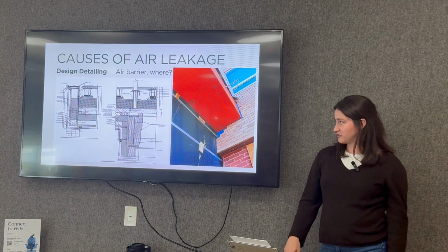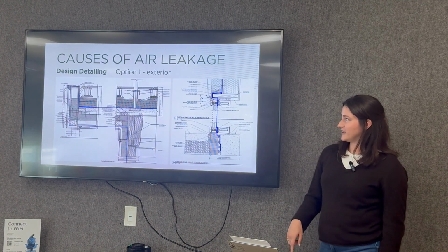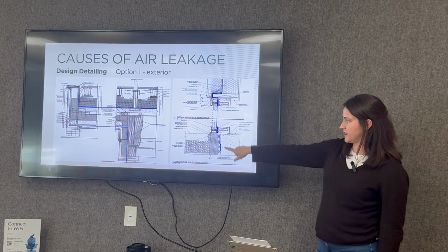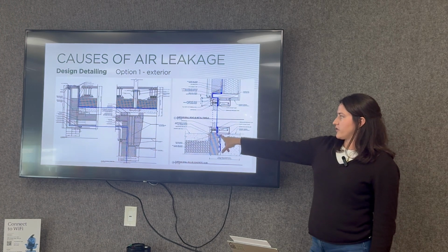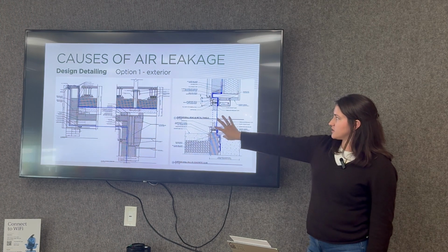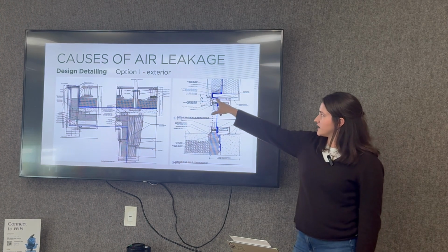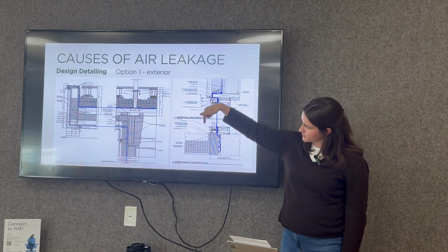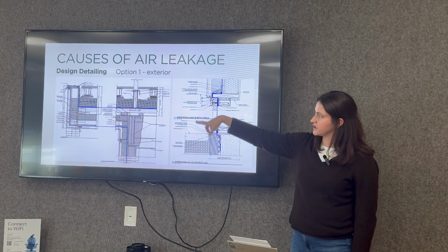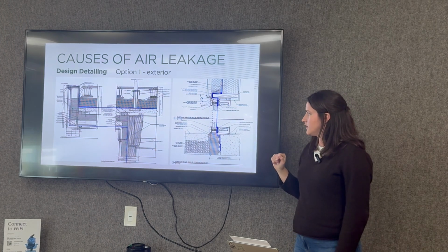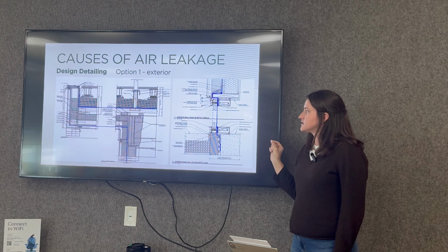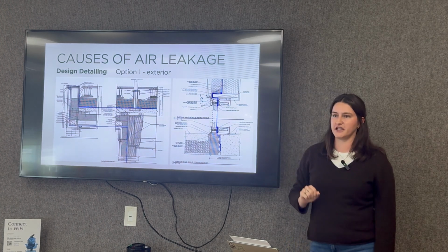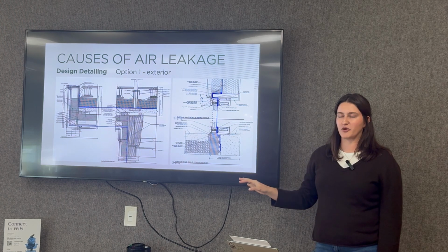Yeah, so that's one option, providing your air barrier fully at the exterior. So you're connected here up with a membrane and then a silicone sheet to the curtain wall, which is your air barrier, and then you connect it with membrane up to the soffit. And then your exterior soffit board is lined with the air barrier, which then connects to the roof vapor barrier. Does anybody see how this in and of itself could be risky in terms of air leakage in practical application?